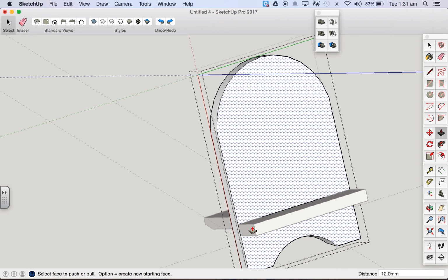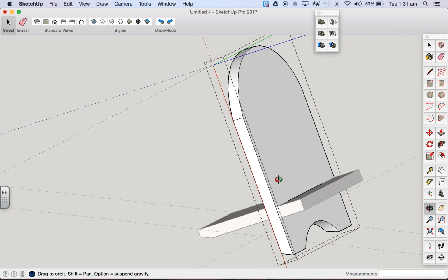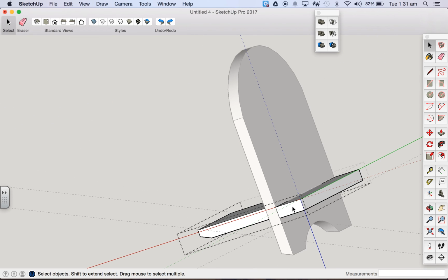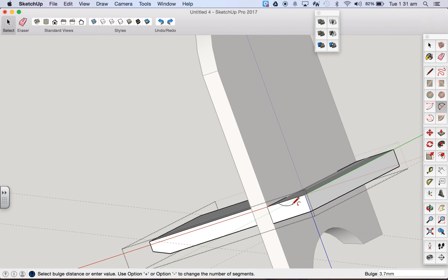And finally, a little groove on this front surface here on the side, going right through, will serve to hold the iPad in place. So you just move down in there, double click on that to edit mode. I'm going to draw an arc from there to there and down. Now I've drawn that there, I can push-pull that to the other side. Voila.